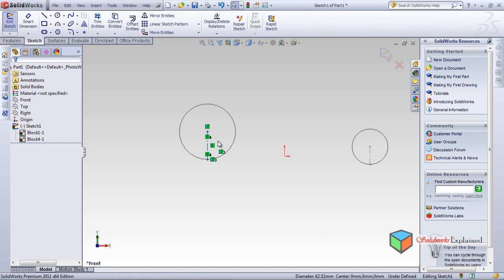Here when you click the edit block, you can see the leftmost toolbar opens, but I want to add this center line into this block, so that becomes difficult for me. When I click here, both lines should be selected, but in this case it's not happening, so I will delete this thing. I also delete this center line. Also want to delete this, delete again.